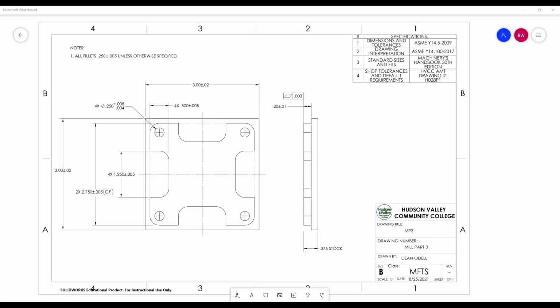Let's get our speed and feed information and cutting tool information in. We are going to end up using a 0.375 mill. The reason for that is it gives us the program. If we use a 1/2 inch end mill, the program will look like this. If we use a 375 end mill, or an end mill with a smaller radius, the program will actually follow and look like a radius. You want that, otherwise you get chatter when you have those stop points. So we're going to use a 3/8 cutter with 4 flutes.